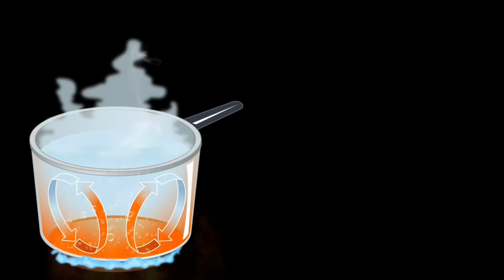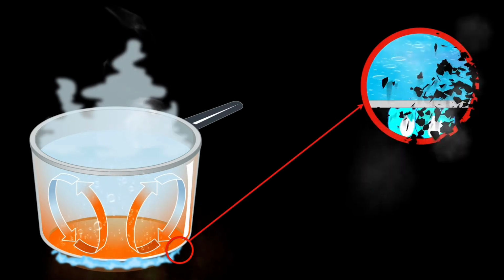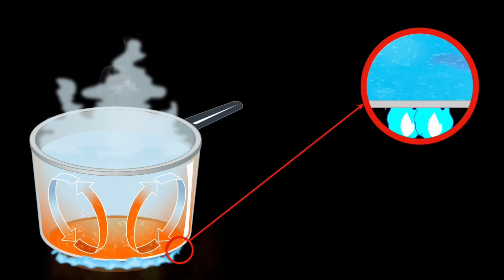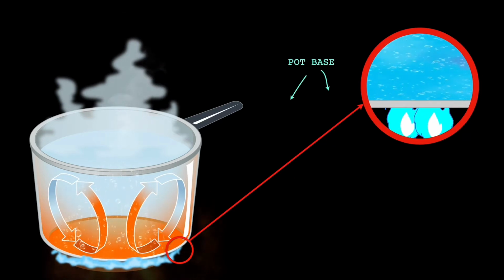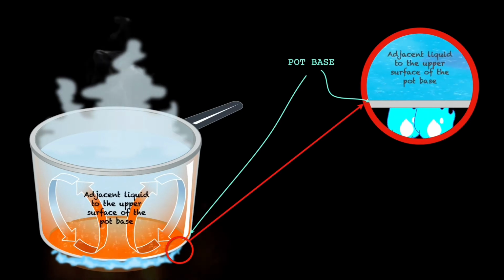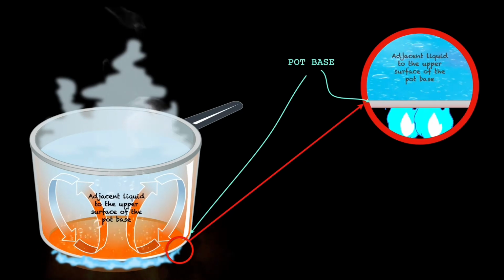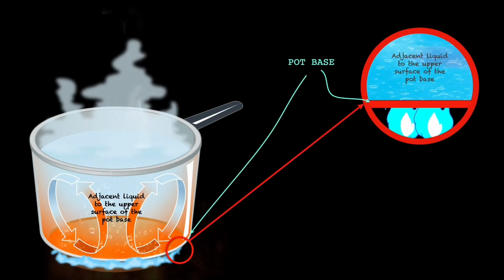Convection is the mode of energy transfer between a solid surface and the adjacent liquid or gas that is in motion. It involves the combined effects of conduction and fluid motion. The faster the fluid motion, the greater the convection heat transfer rate. In the absence of any bulk fluid motion, heat transfer between a solid surface and the adjacent fluid is by pure conduction.